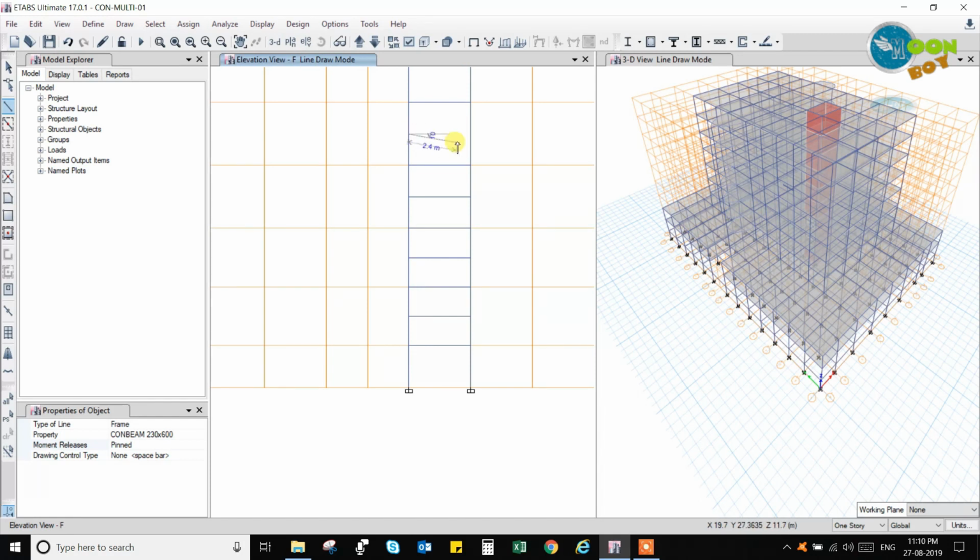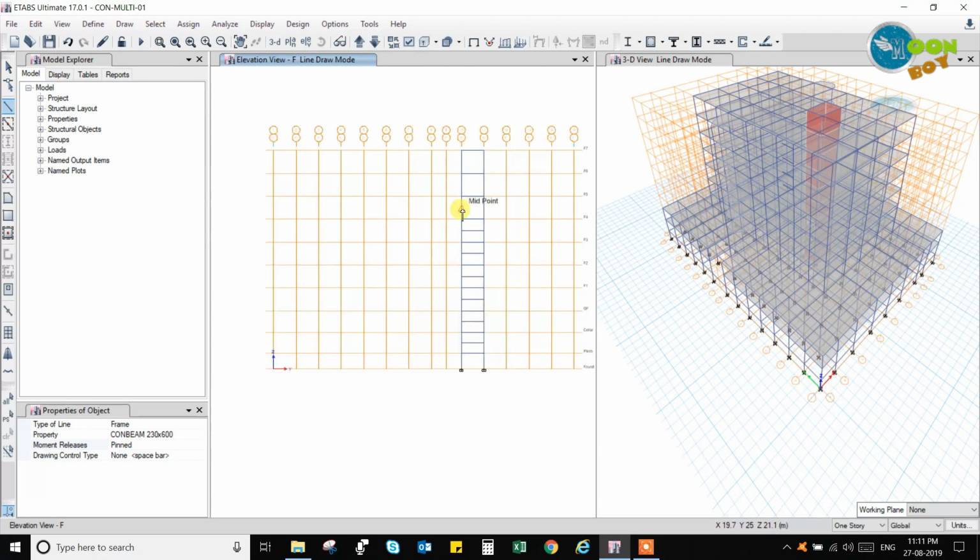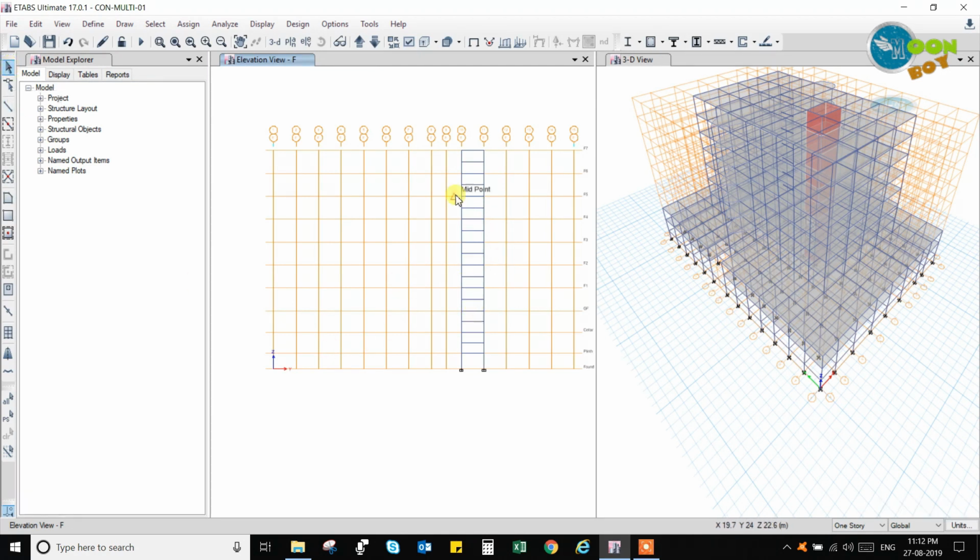It is very necessary to draw midpoint one by one floor, because if your floor stories height is changing, so this mid landing will not be at the center of the column. Or you can splice the column. You can draw a grid at every mid center of the floors, and you can have that grid line, and in that grid line you can just click, and the beam will be drawn on that grid line. So there are several different procedures for drawing these kind of beams in between. So just go out of the draw menu. Now you can see that all these beams have been drawn.